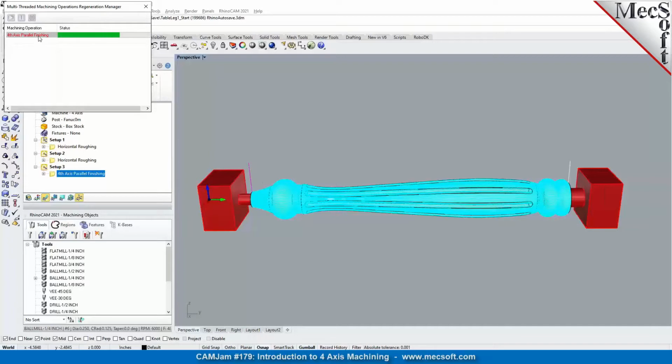So the across cut pattern would take a little bit longer time to generate compared to the along axis cut pattern. So as you can see, the toolpath is being generated. And once the toolpath is generated, you'll see the result of the toolpath in a moment. As well as, not just generation on the machine here, but also on your machine tool as well, because you're spinning the axes constantly when you're doing that. While the along, you can think of it as locking the axes, running the tool, and then turning the rotary axis, and then locking it again and running it again. So that's much quicker, but you might not get the finish that you want.